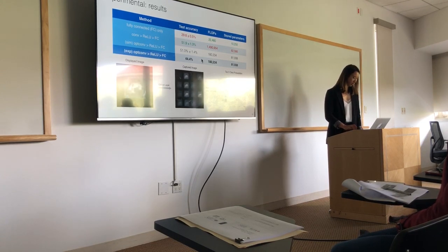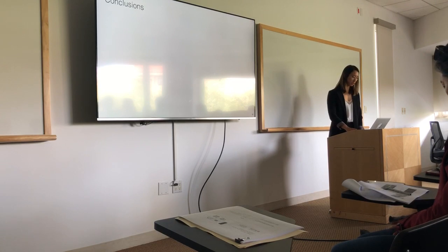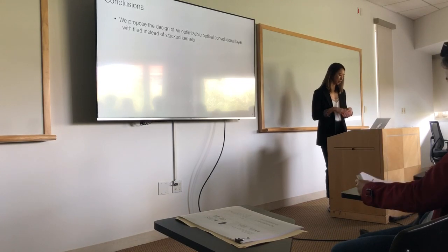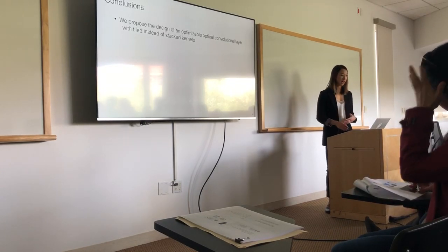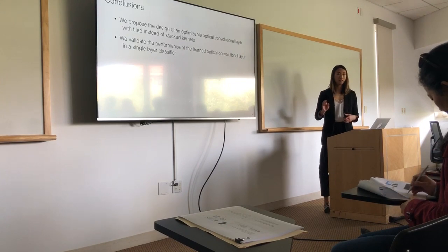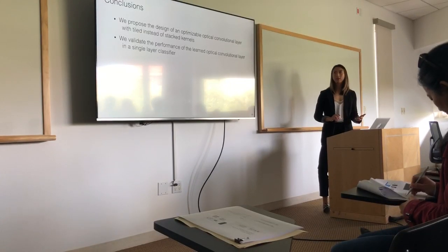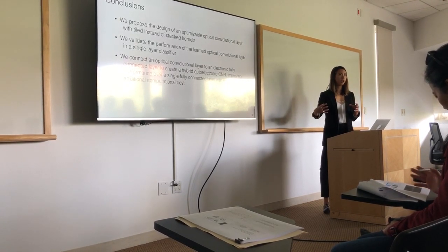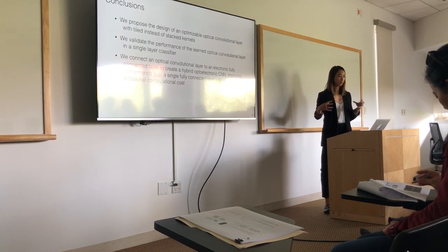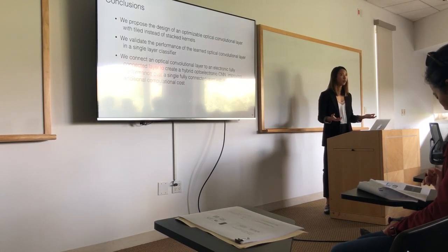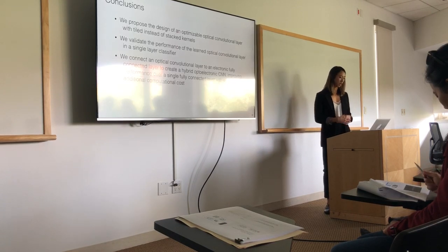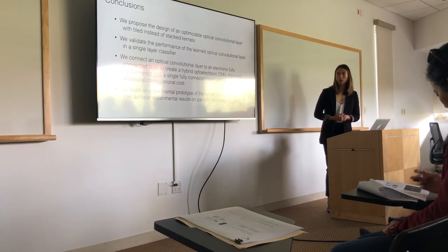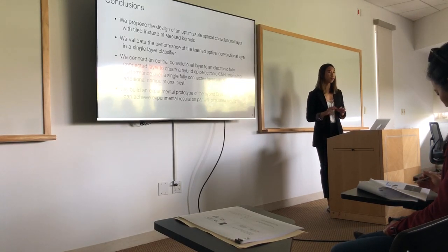Okay, so from this project, we make a couple of conclusions. First, we have proposed this design of an optimizable optical convolutional layer with tiled instead of stacked kernels. We validated the performance of this optical convolutional layer first in a very simple single layer network. Then we connected this to an electronic fully connected layer so that we have a hybrid system. And then we showed how that can improve the performance with minimal additional computational costs. Finally, we built up this experimental prototype and showed that we could achieve experimental results on par with the simulated results.